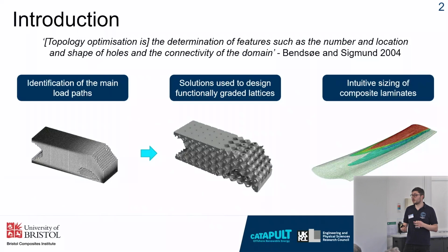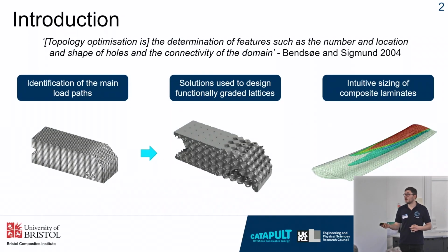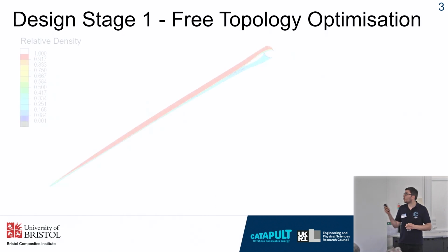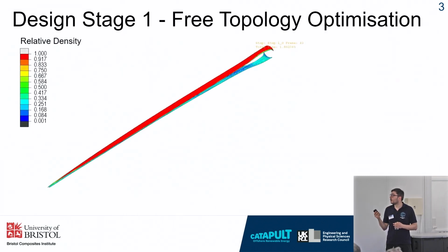The concept would be that we build these lattice structures using 3D printing, and then we lay up the composite laminates on top of these printed structures, which would mean you'd have an internal structural mold, hopefully removing the need for composite tools made out of metal. These can be quite costly and time-consuming to use, especially for wind turbine blades, which is what my work is mostly focusing on.